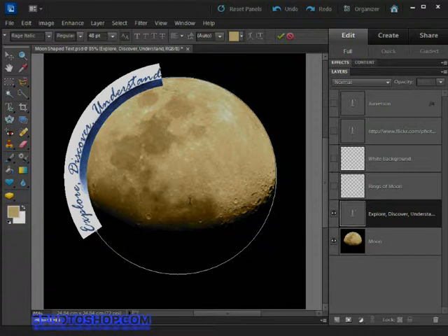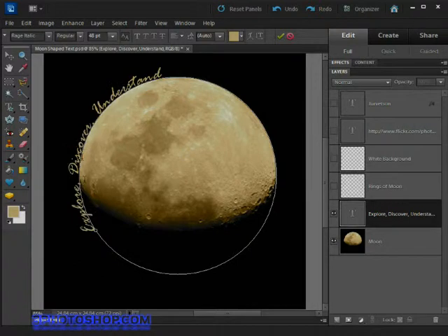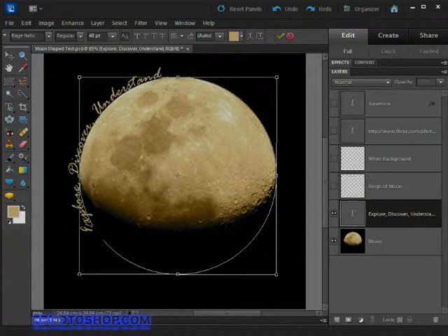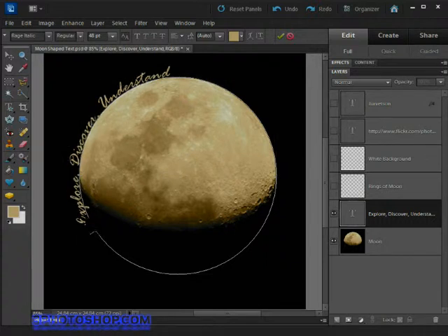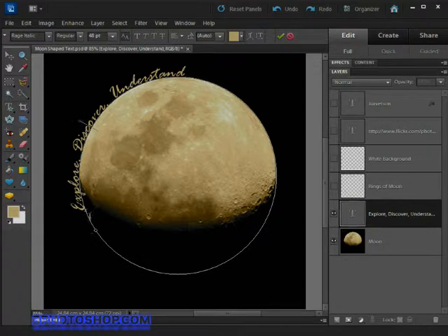Now let's click inside the text somewhere, like so, anywhere will do. And now we can control or command drag this little circle representing the start of the text, and that will indeed create a new beginning point, which is now represented by a little cross. So let's move that just a little higher than the circle, which is now representing the end point, and release. So we can see clearly that the cross represents the start point, and the circle all the way around here represents the end of the text. And in this case, we're not filling most of the available space awaiting text. So just for housekeeping, let's drag the little circle all the way around the shape until we get somewhere near the actual end point and release.